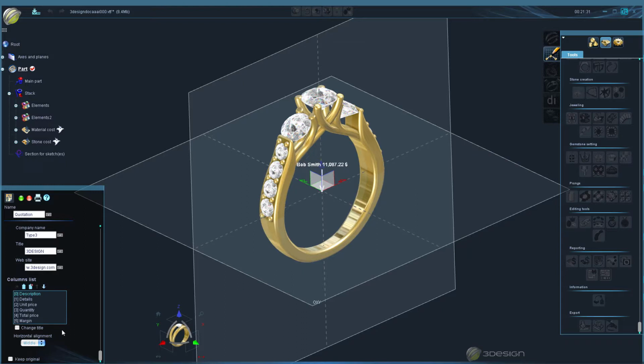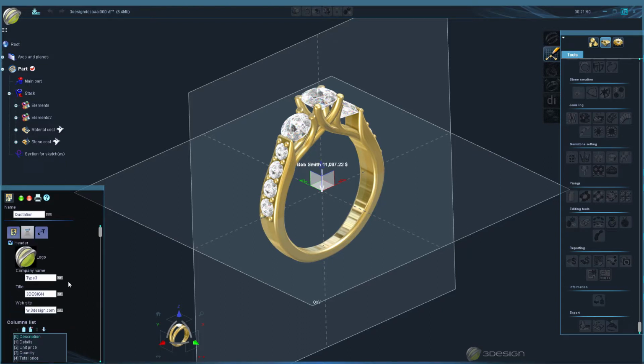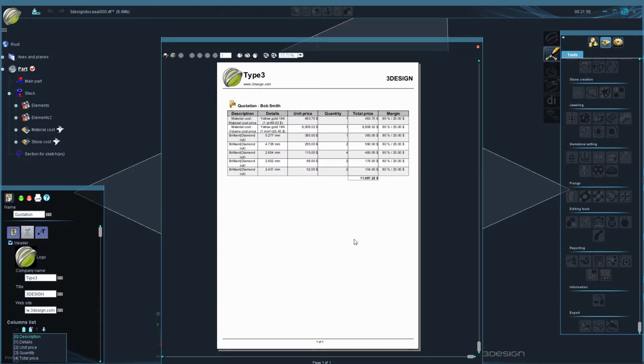Again, you may want to check your column list here, remove anything that you don't want the customer to see. If you're using this for a customer report quotation, you probably just want to show the description, maybe some comments and totals, not the actual percentages of markup. But for an internal report, you might want to have all the data. So again, you can customize these as you see fit. Otherwise, we generate the report and we see the breakdown from the other two reports into one nice list, giving me my totals with the grand total and my markup percentages, etc. here. You can see my fixed cost is added in there as well.